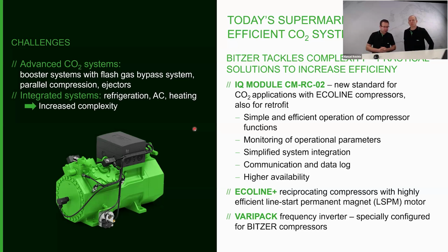When we implemented the VARISTEP technology, we also added our Bitzer OLM IQ. That's our oil management system, which works in combination with the IQ module. This oil management system can record the oil level in the compressor. It's not only a device that feeds back, it's also a digital sight glass you can see. And you can see the sight glass history in the data log over 2 weeks.